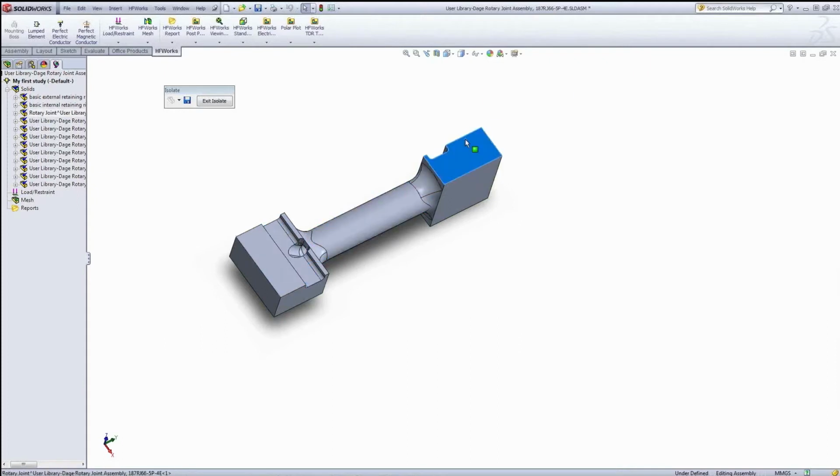So all these surfaces need to have a boundary condition associated with them. Now the software knows when you have a metallic part touching the dielectric or non-metallic part, it will apply a metallic boundary condition to that surface. So this will simplify my analysis considerably by doing things this way.